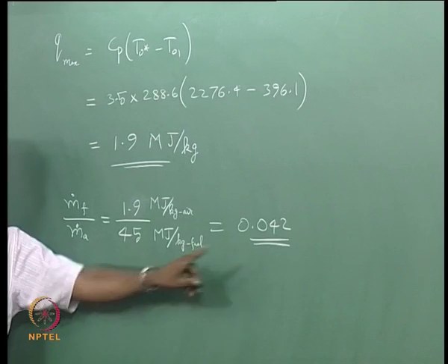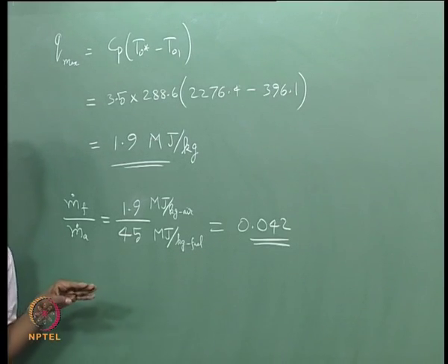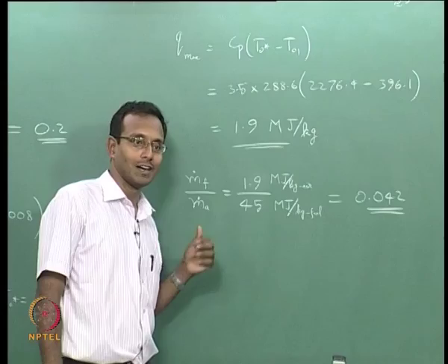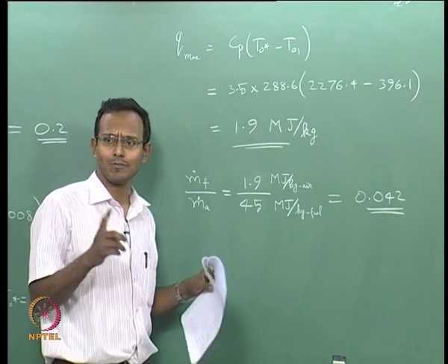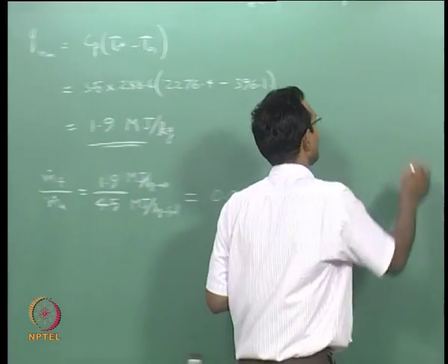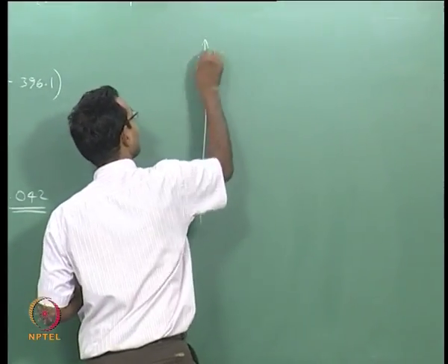That is, you are having thermal choking coming up suddenly because I cannot heat any more. If I heat any more, what happens? I am going to have M equal to 1 forming, and suddenly the flow rate decreases everywhere and it jumps to a different curve. Oh, did I talk about that part? Maybe I missed that. So I will just go and do that one little thing, just a little detail.